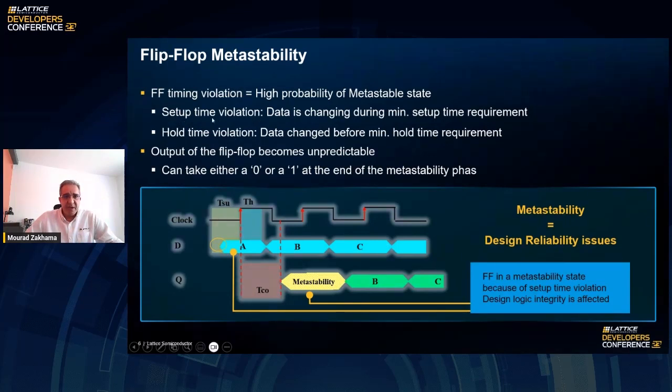What we mean by setup time is the data changing during this minimum setup time requirement, like we have here in this situation, where in the setup time requirement, the A input is not stable enough, or not stable long enough, to be captured by the clock and be available at the output. In this type of situation, the output that will come from the clock after the clock to out, the TCO, is unpredictable. There is a metastability situation. So it could be 0 or 1 independently of the input. And that's what we try to avoid.